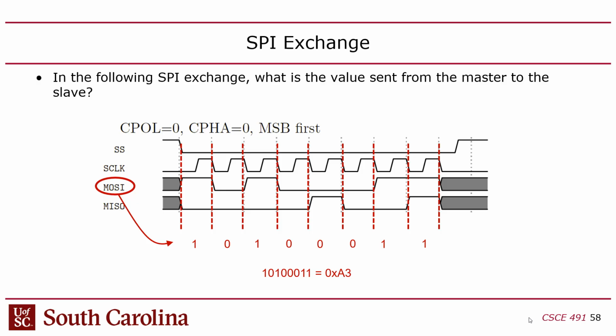So basically the idea from the slave side is as soon as I see slave select dropped, I have to get MISO set up as quickly as possible because the clock's coming, right? And the master is expecting to read on the first edge of the clock. And as a slave, I haven't even seen the clock. I haven't even seen the first edge yet. All I know is the slave select is down. So I've got to get going here fast, right?